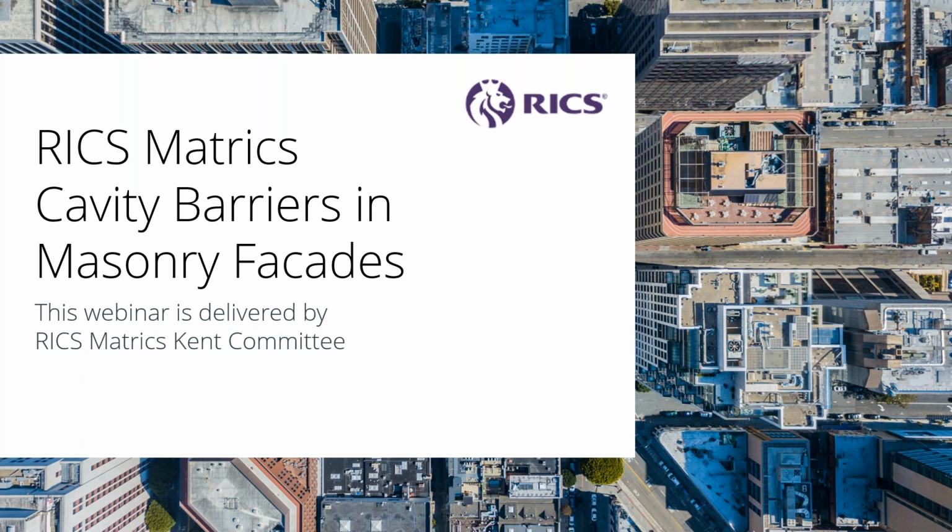In terms of it stopping water getting through it, it won't do 100%. So if you're looking at it, for example, as the fire stop inside the building, say behind a curtain wall, and you've got people at the end of shifts sweeping puddles directly on top of the fire stop, as unfortunately is all too common, the fire stop itself will let water through it, but very gradually. It'll be a very slow drip.